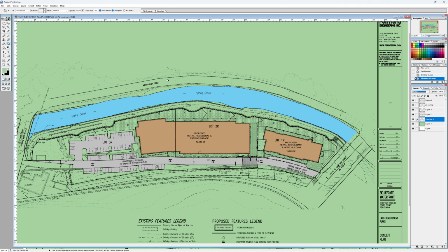A lot of times one of the effects I usually add to the lawn areas is to add some sort of shadow to them. Again, this just comes back to me messing around with different options, and I came up with this one that I liked. One thing in Photoshop, you can hit the Control button down and it changes your icon to be the selection tool. So I would select everything on that layer just like that.